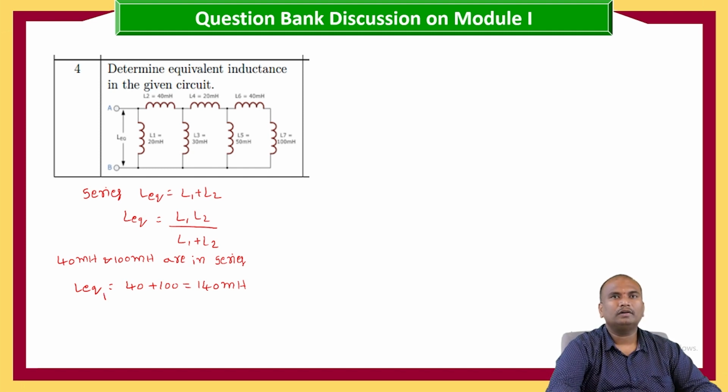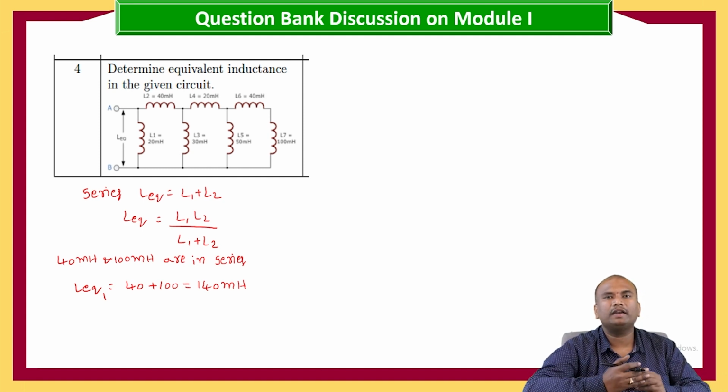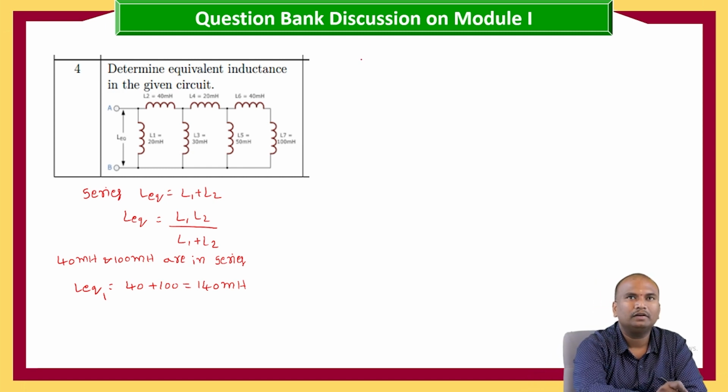Now we got the L equivalent 1 in place of 40 millihenry and 100 millihenry. Now we are replacing these two inductances with a single inductance, that is of 140 millihenry.